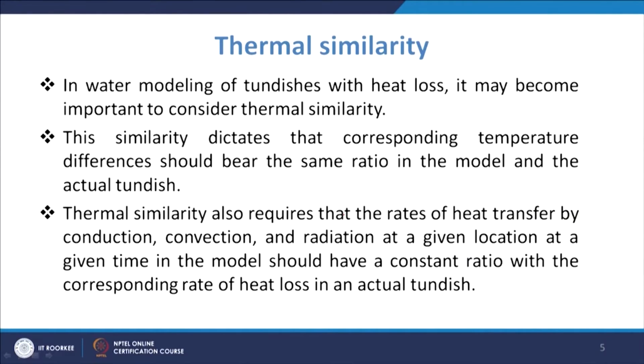Thermal similarity also requires that the rates of heat transfer by conduction, convection and radiation at a given location at a given time in the model should have a constant ratio with the corresponding rate of heat loss in the actual tundish. So, similar to the temperature, it also applies for the heat transfer which is taking place by conduction, convection or radiation.